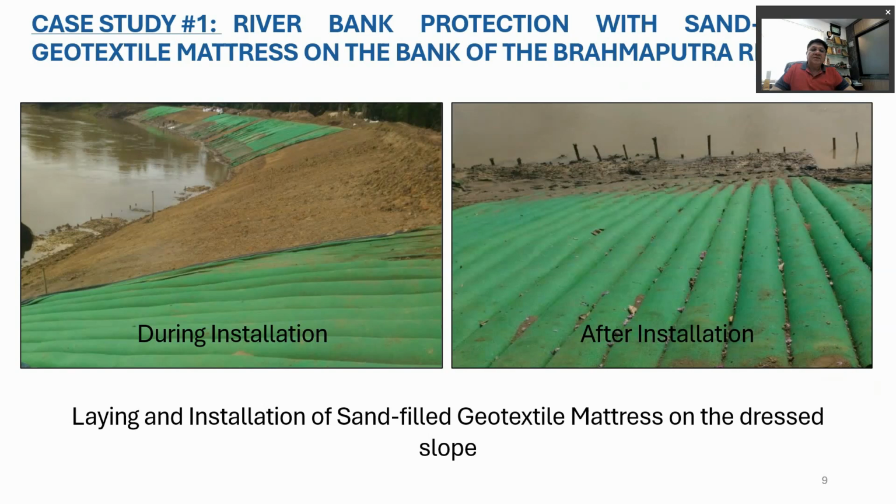So you can see in the installation photographs how the tracing has been done. Then the anchor trench has been provided at top and bottom, and these mattresses are laid, filled with locally available sand, and used for the application. Siltation is observed after a certain period of time, to avoid UV and all these phenomena.